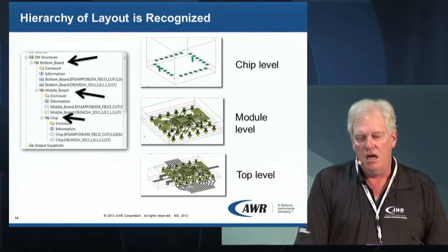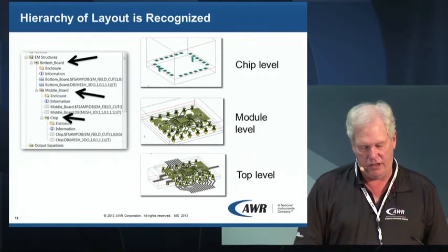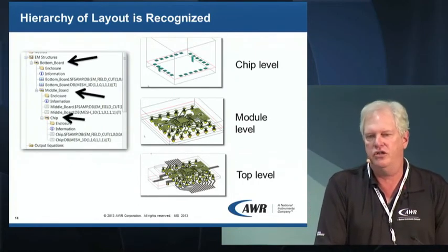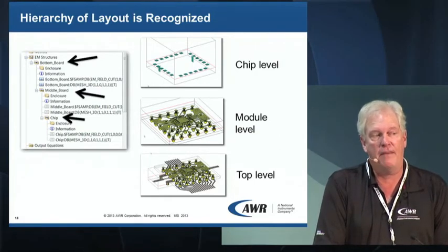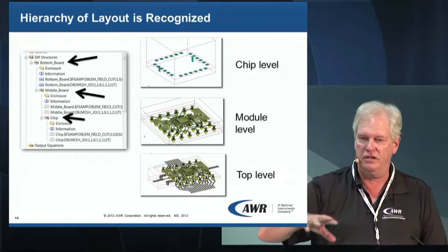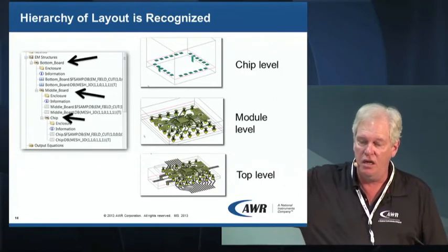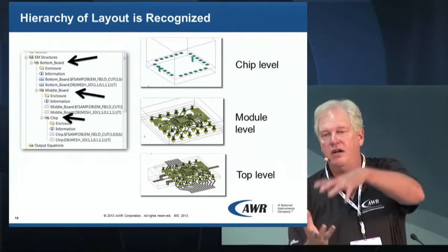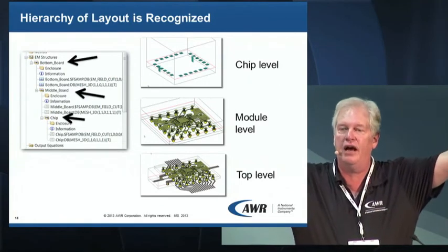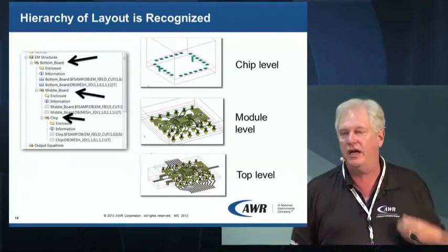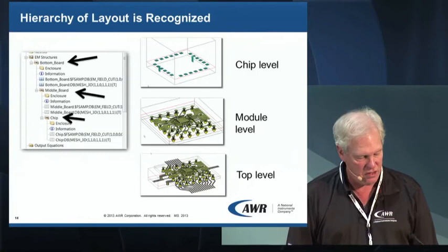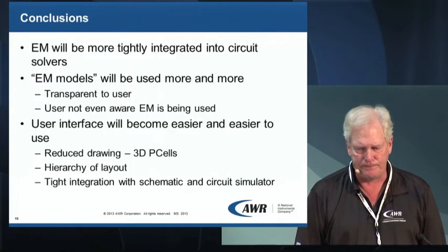Okay. Another thing we can do in the circuit simulator is hierarchy. Why on a schematic do you use subcircuits? You can reuse them, etc. And what happens in the layout? You have subcells. You draw that inductor once, can keep reusing it. In this circuit, they have a chip level, a board level, a module level. With hierarchy, you can keep building up the layout, then EM simulate at whatever level you want. Okay, again, very easy to use, same as the circuit flow.